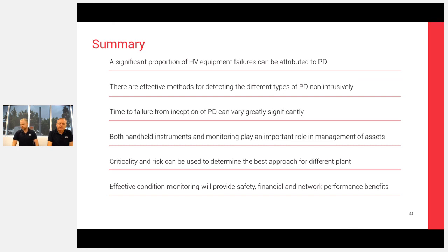Cables, another one. If you had a defect inside the solid element of the XLPE cable, that potentially will accelerate failure very, very quickly, before the monitor really has had a chance to see an upsurge as well.